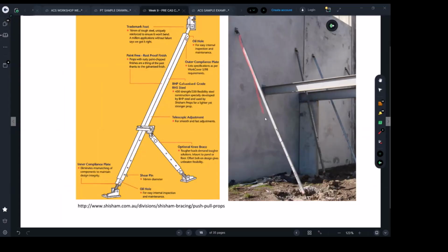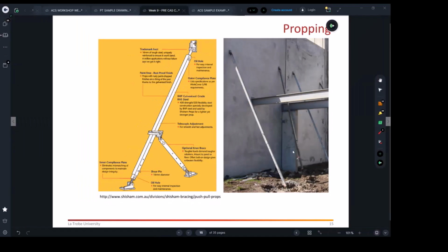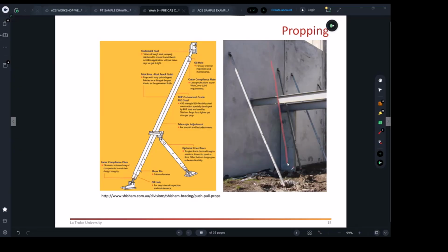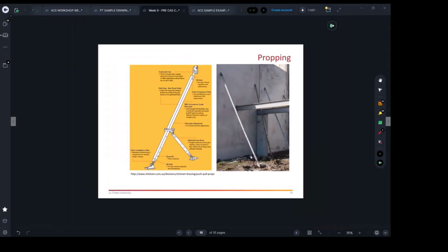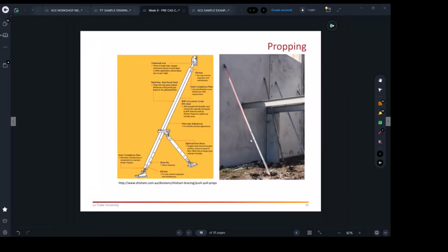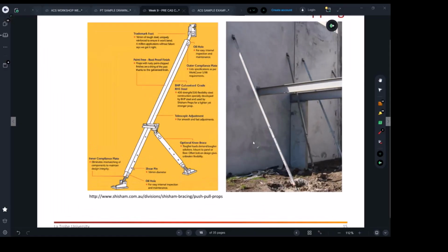So there are engineers who look at what we call temporary works. They're going to be checking the placement of those elements, making sure their ratings are correct. So these panels will require, for example, maybe 10 kilonewton capacity, and they will just make sure the ratings are appropriate.